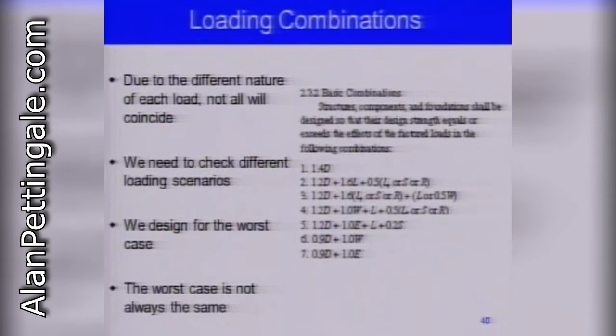Then here, we also have the load combinations, and these are from ASCE 7 of 2010. If you remember the previous version of 2005, the coefficients in these load combinations have changed, but they have also changed the actual loads themselves. So it used to be 1.6 times the wind, for instance. Now it's 1 times the wind, but the wind itself changed. So at the end, it comes down to being essentially the same load. But you need to be careful when you calculate this.